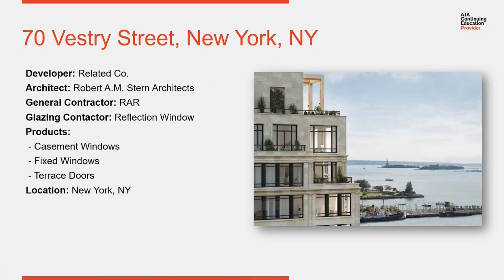These modules, consisting of limestone on the exterior with the receptors built into them, were stacked one by one. And then once the modules were in place, casement windows, fixed windows, terrace doors, different components were brought from the interior and set into the openings, into the receptors, and then stops snapped from the interior, and it's all closed up. Nice looking building, very good looking project, great example of modular construction.